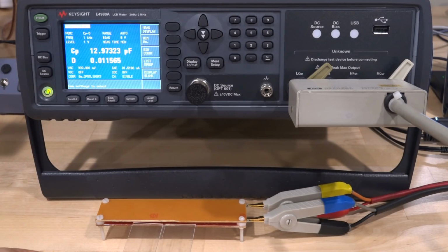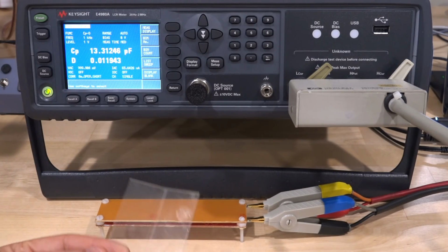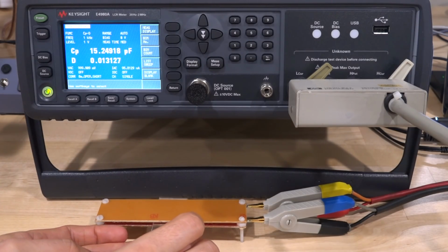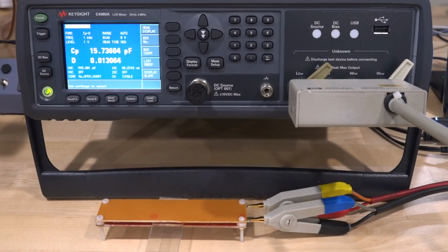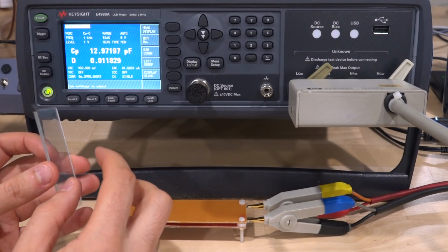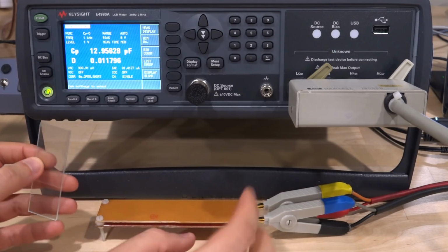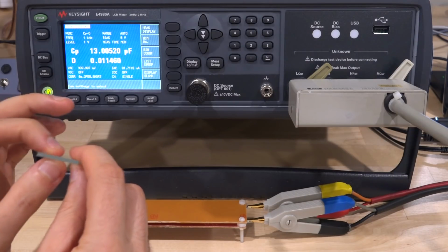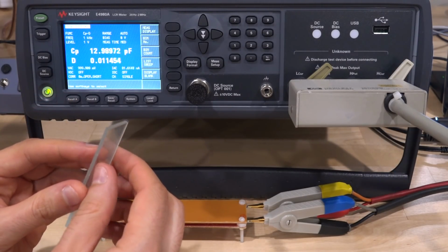So we're going to try it flat first, in the middle. We get 14.7 picofarad, okay? So let's remove it. We're going to fold it over, try exactly the same thing. In the middle, look at that, 15.5 picofarad. So it's different. It's interesting to note that it's more impactful in this capacitor because of its total dimension and everything to have a thicker dielectric with a higher dielectric constant than if you have it flat.